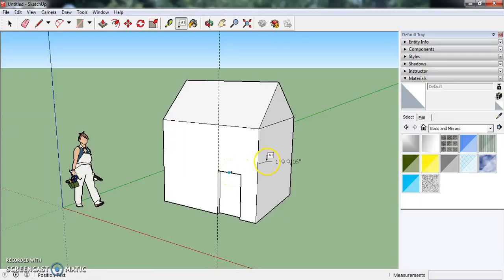You click on one point, pull away from it, and right over here we can type in like a measurement, or let's say, for example, we want to label it door. And once we click out of it, right there we have a leader line, which is known as this line, that goes from the door, the word door, to the door itself.